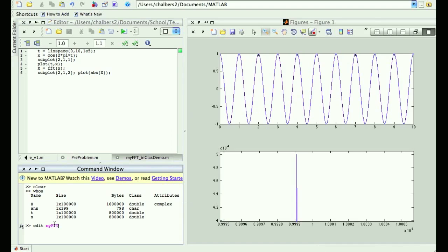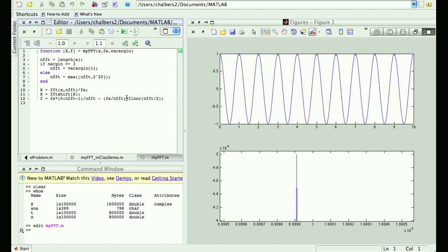Here's what you're going to do. You're going to pass into it your signal x that you want to take the Fourier transform of, and you're going to pass in the sampling rate of your signal. I'll tell you what that is in a second. Ignore this stuff right here. That's just some get out of jail free stuff I did in case of more advanced uses, but we're not going to use it. Does that look familiar? Just take the FFT of the signal. I scale it by sampling frequency. Don't worry about that. That's just a divide.